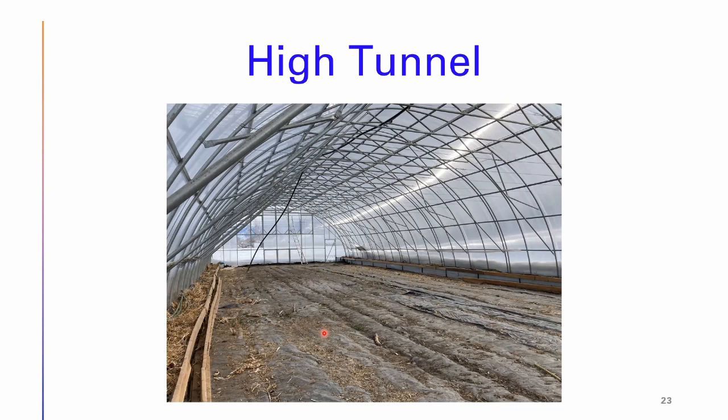And let me put that into contrast. 1 pound of water raised from like 200 degrees Fahrenheit to 201 degrees Fahrenheit, that's 1 BTU. But the amount of energy for 1 pound of water to transition from water to steam is 944 BTU. So it's this phase change. It's this huge phase energy.